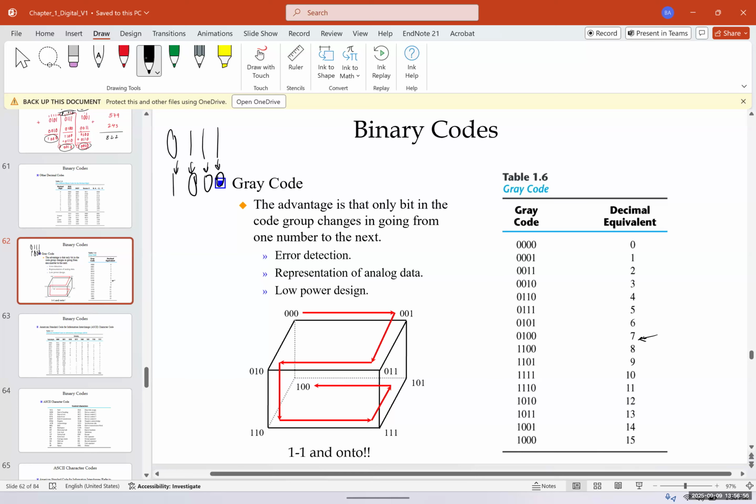We know that each of these binary digits represents a level of voltage. So when you go from 0, 1, 1, 1, you're going from 0 volts, 5 volts, 5 volts, 5 volts to 5, 0, 0, 0. So you have a huge change in the voltage. But if I go, for example, from 0, 1, 1, 0 to 1, 0, 1, 1, I'm just changing 1 bit voltage. So I'm not changing all the 4-bit voltages, and I'm going to consume 1/4 of the energy compared to the other one.